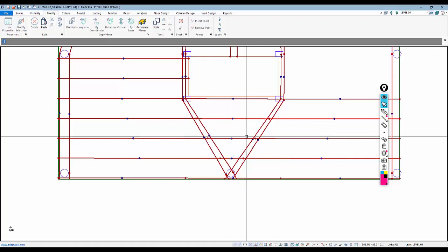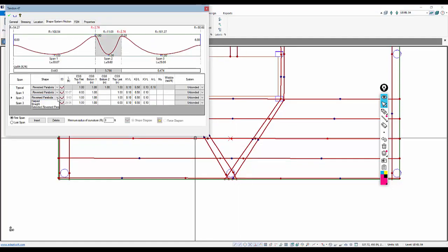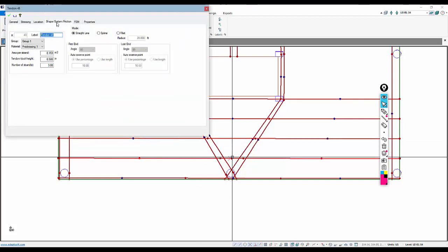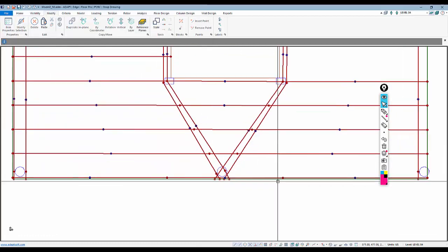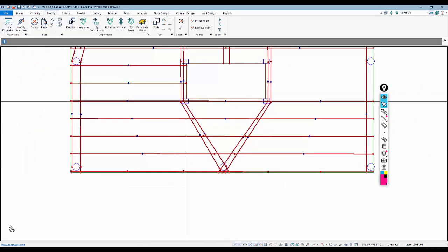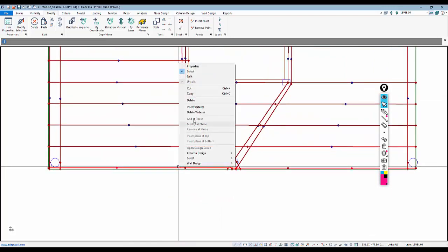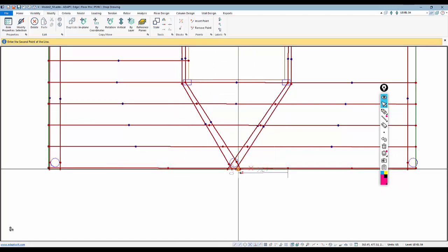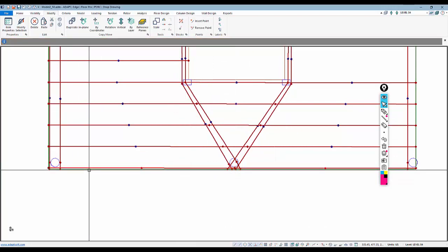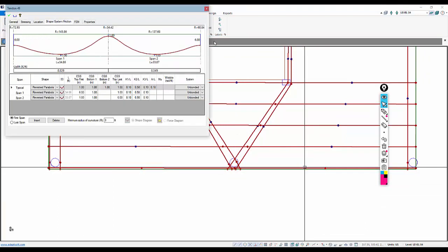We don't really need much drape between these two bands, so I'm going to take this tendon and, for that middle span, just run that straight over the two bands. The same thing here. And finally, for this one, these two bands converge, so really we have a two-span condition now. I'll right-click and delete out one of the spans. So I'll slide this control point over. Now we have span 1 and span 2, and if I double-click on that tendon, we should see that like so.